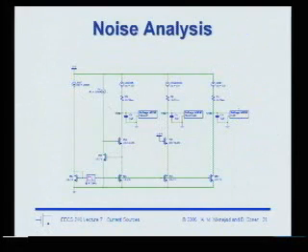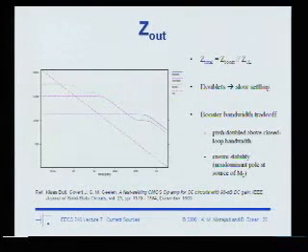Okay, so here is actually a plot of the various output impedances. So this blue line, if it shows up on your screen, the bottom curve is your regular device, okay? And this pink curve is your cascode. So you can see the cascode has quite a boost on the log scale. Notice we're going from 100K to 100M. And the price we pay, of course, is that the bandwidth is not quite as good as the regular device, because we have basically some extra capacitance on that cascode node.